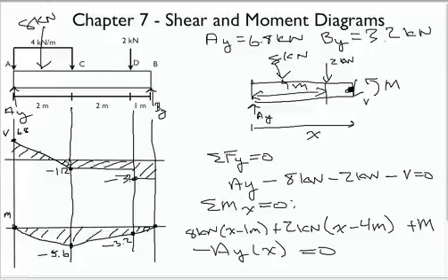All right, so what we're left with here is basically a graph that shows how the shear changes through the material, and then a graph showing how the moment changes as we travel along the beam. So again, these represent the continuous distribution of shear and moment throughout this beam, which is the goal. Now, some of you may be saying, hey, but when we make this cut, there's all these forces over here that we look like we're throwing away. What happened to those? And the answer is those are contained within the two reactions.